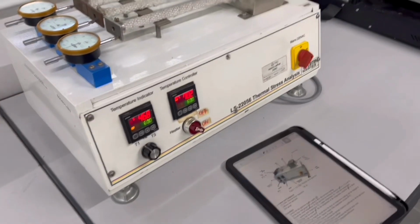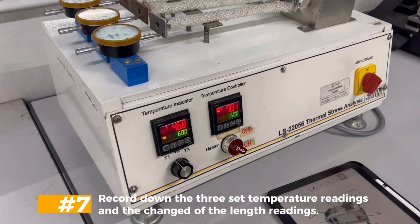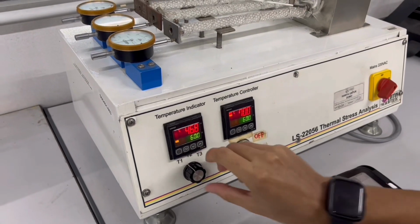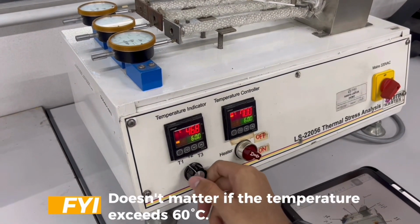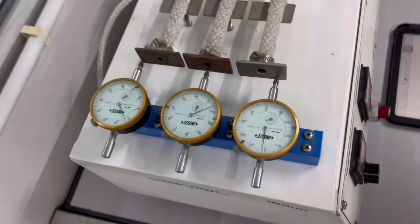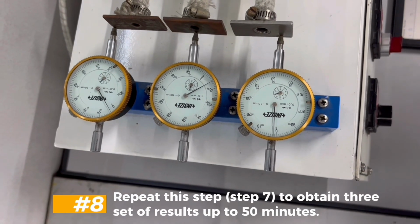After 10 minutes elapsed, record down the 3 sets of temperature readings and the change of the length readings. For your information again, it doesn't matter if the temperature exceeds 60 degrees Celsius. Then, we need to repeat this step to obtain 3 sets of results up to 15 minutes.